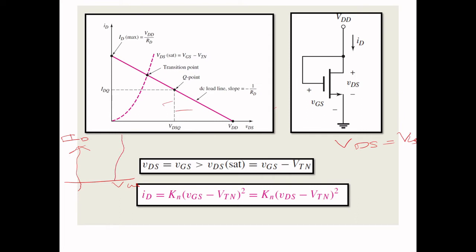So you can see this is a region at which your channel is not created and it is trying to create. So once your VGS equals your threshold voltage, from VGS only you are taking. Once your VGS is equal to the threshold voltage, the channel is created, then only the current starts to produce. Okay, this is one idea you keep in mind. The other thing is your VDS is equal to VGS. So these are two things.